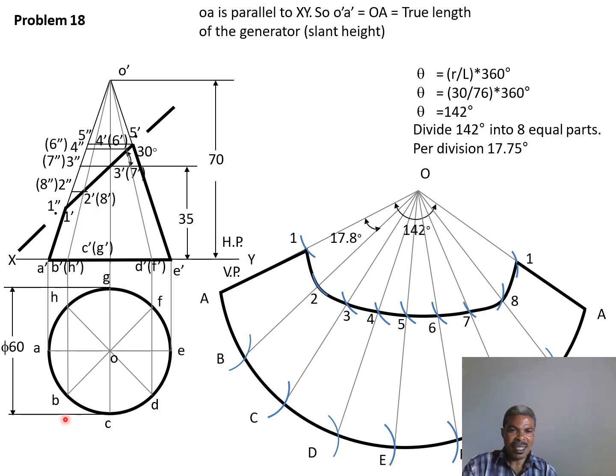you can see this point B and H, they are in line, mind you. A line is projected until it touches the horizontal for our base. Then this point H is termed B dash, and H dash is projected up until it reaches the apex or point O dash.